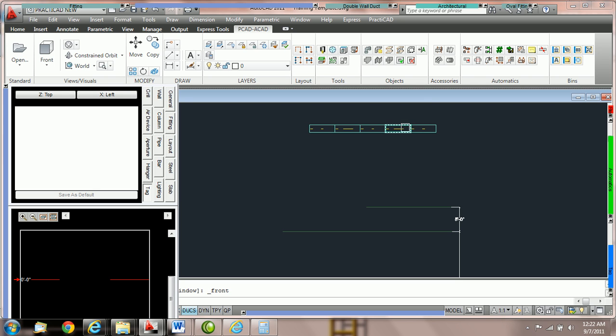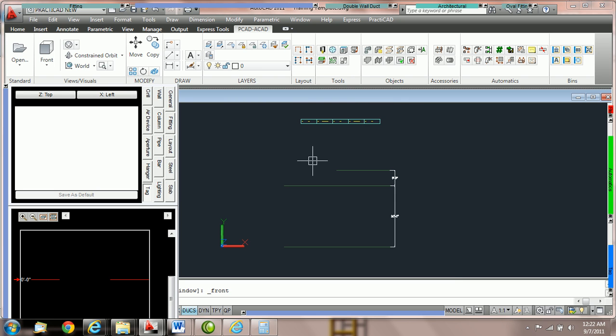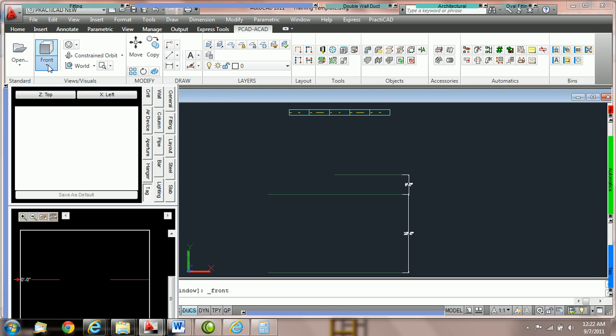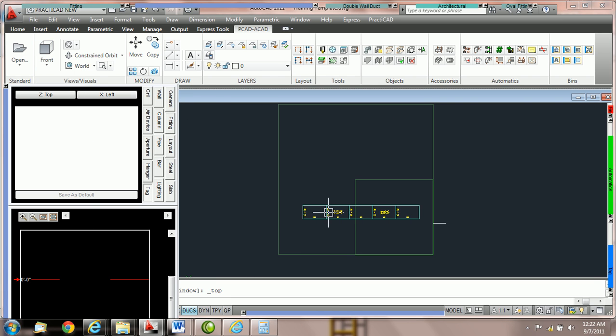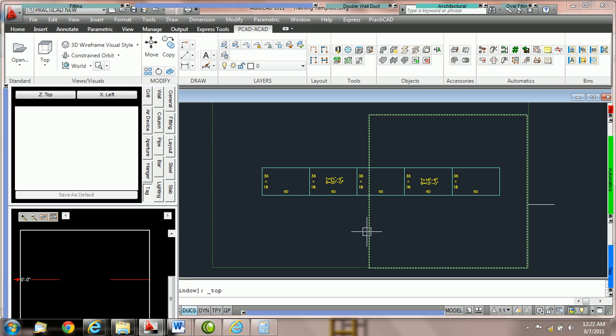However, each of these is being tagged based on the reference point below it. So the drawing is correct, the tags are correct, and when we go to export this drawing for the BIM model, this duct is going to be at the right elevation. So very important. Once again, we can toggle between relative bottoms and tag to different reference points.